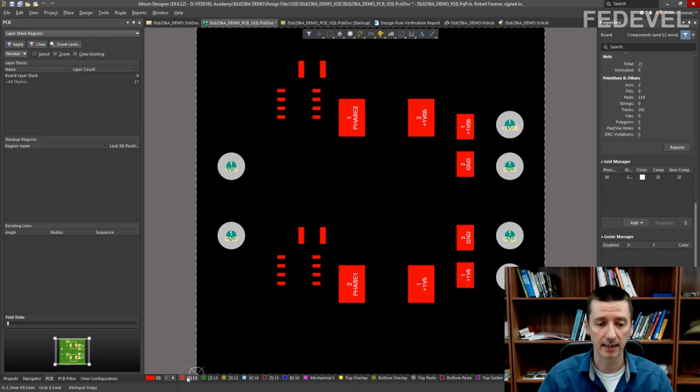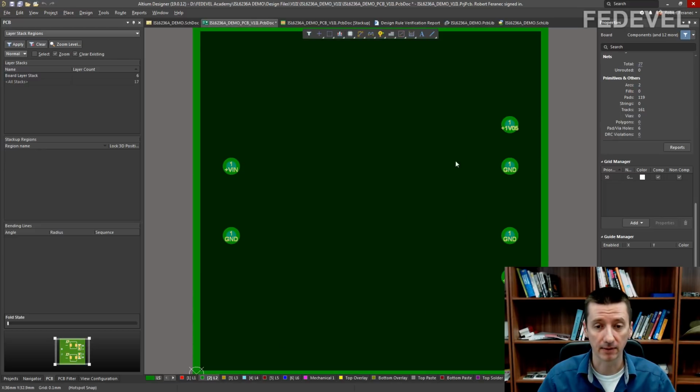On the signal layer, by default, the layer is empty, and anything you draw on the signal layer is going to add copper. And because by default on this plain layer there is copper, we would like to assign this copper to a net. And we would like to have ground planes on the layer 2 and layer 5.